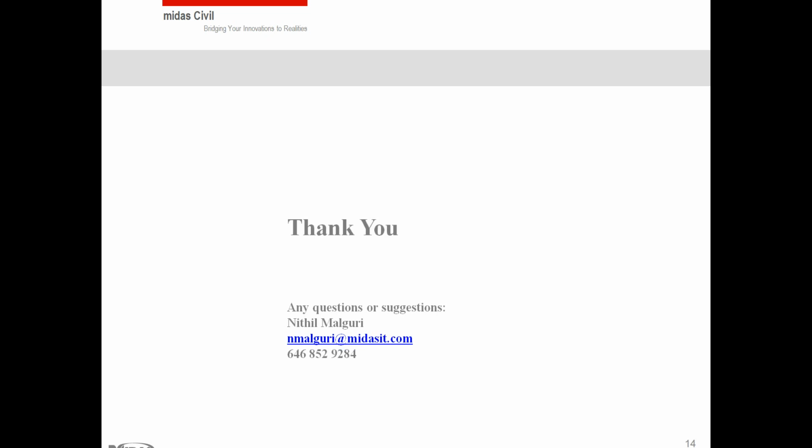And there is one question by Mr. Ved Sharma. The question is, how do you input different element releases for continuity at pier support for live load only? Well, Ved, we have already talked about it. You can use beam end releases for that. So we did discuss it in detail. You can use beam end release, and you can tell the program that for dead loads just use simply supported, and for live loads use continuous nature.